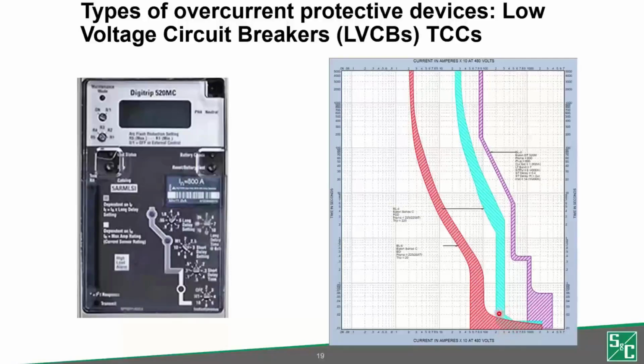However, this question of miscoordination can usually be resolved by referring to manufacturer's documentation, the coordination tables that we discussed a few slides ago, wherein the manufacturer would publish which two overcurrent devices can be put in series without miscoordinating, as there may be a certain amount of current limiting capability in the source side device versus the load side device.